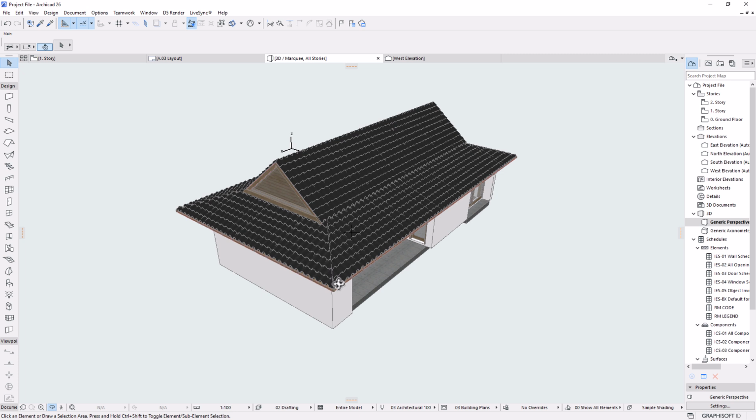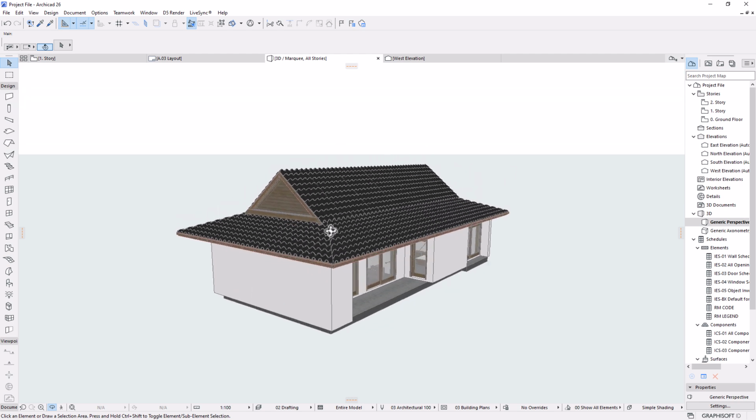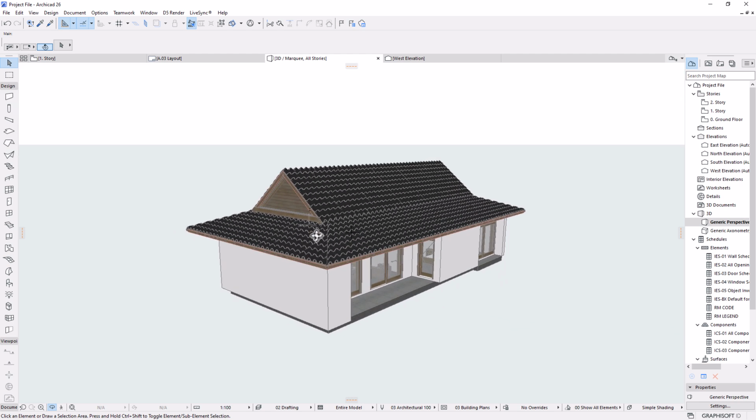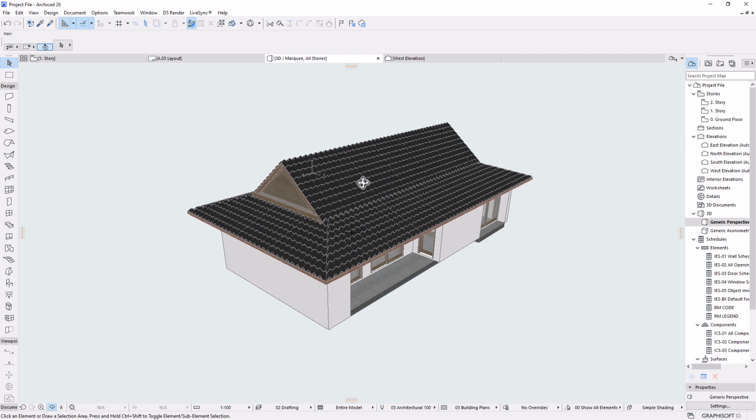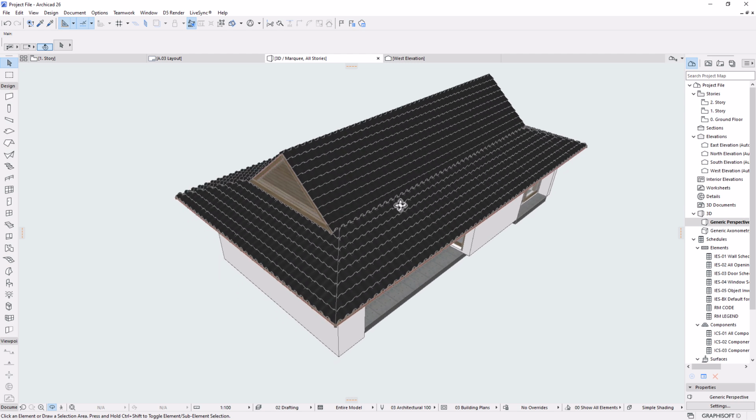Again, I also wanted to indicate that you could use a beam tool to create your roof ridges, especially if it's a complex roof with complex ridges to place, because the method of using a ridge object is manual. But if you have a roof that has too many ridges, it's going to give you a headache. Hence, the beam tool will come in handy. I will demonstrate that in a separate video, because here I want us to focus on creating the best result for this kind of roof design.